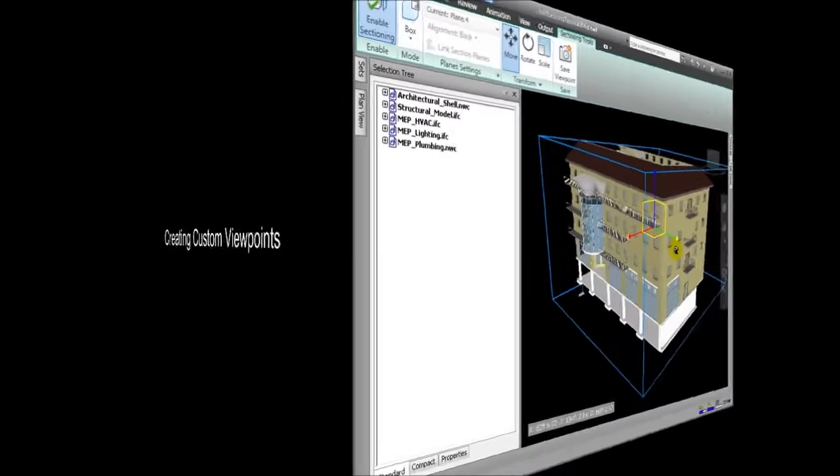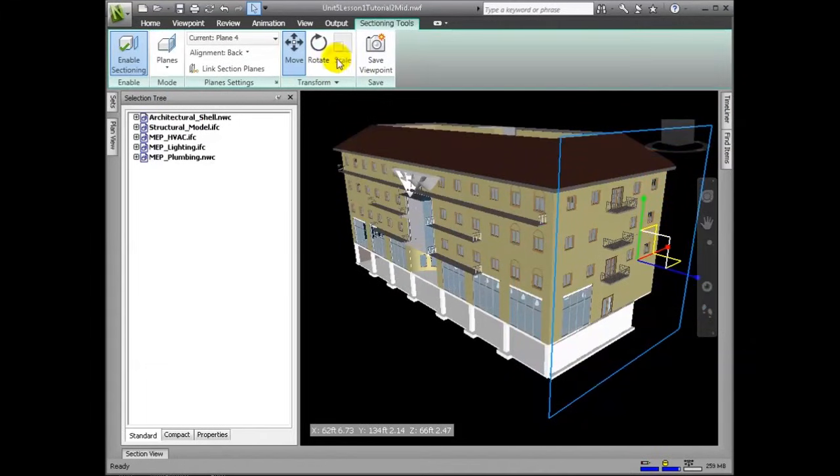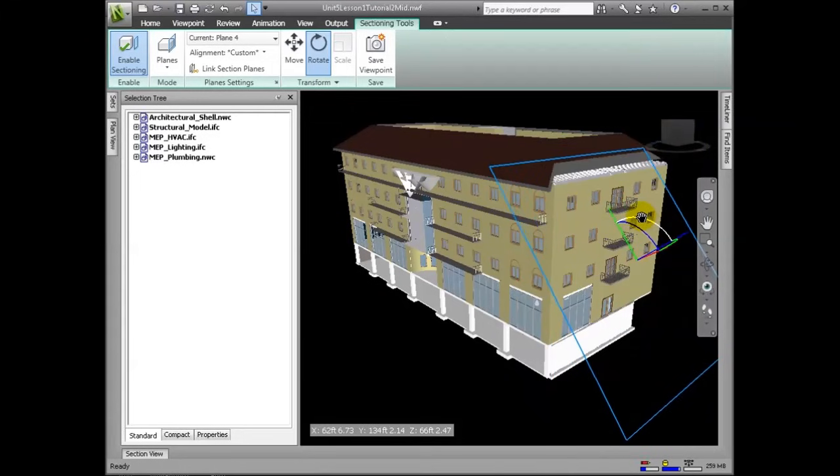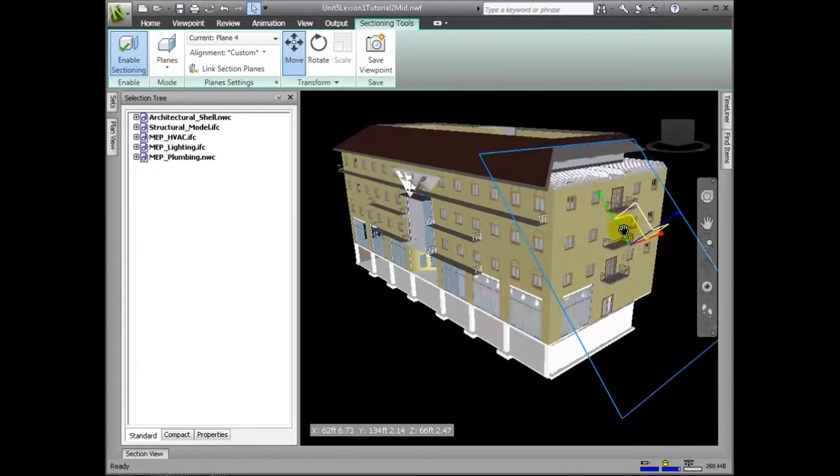Viewpoints are an important feature of Navisworks. They not only allow us to save and return to views of the model, which are of importance, but they can also be used for design review audit trails and for setting up model animations. Viewpoints can optionally retain saved attributes as well, no matter the changes we make in the course of navigating, so that on returning to a viewpoint, the camera angles, sections, overrides, and hidden items are reinstated.